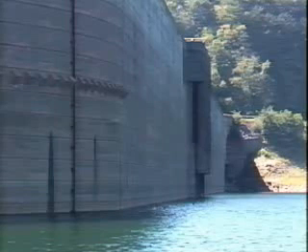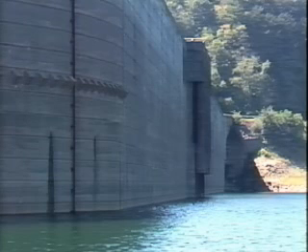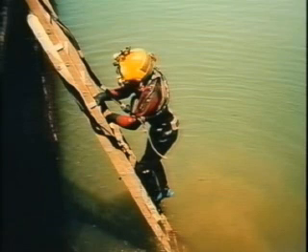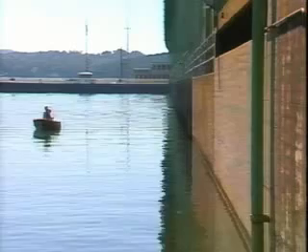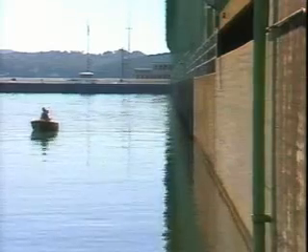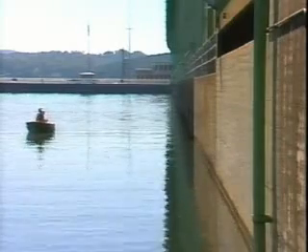Sometimes inspection of the exposed areas of the dam may lead you to believe that the submerged portion of the upstream face should be looked at. In such cases, you can return when the reservoir level is down, if that occurs in the near future. If you suspect a problem that should be investigated immediately, you may wish to recommend the use of divers. Remember, it is important that you note in your report the level of the reservoir at the time of your inspection. One way to inspect the upstream face and upstream abutments is to use a boat.